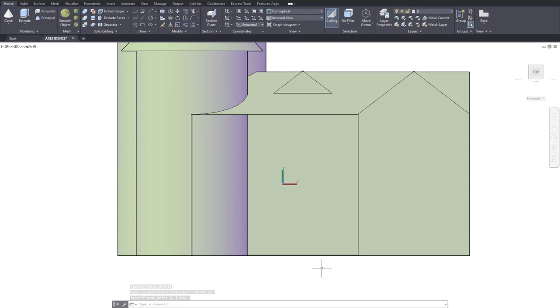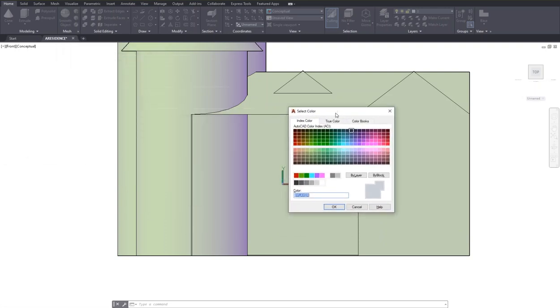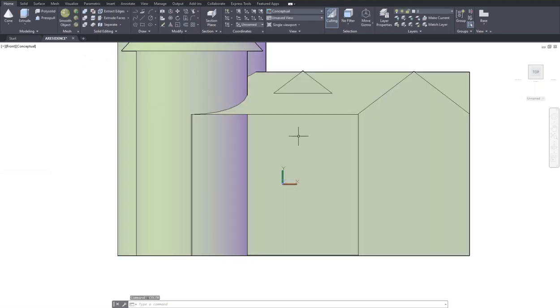Maybe I should change the color to red. Okay. So that I can see the lines. And when I type color command, computer gives me a selection of palette of colors right here. Okay, so magenta, let's go with the magenta. Okay, and let's repeat the line command.